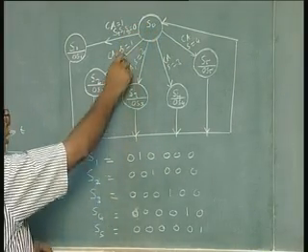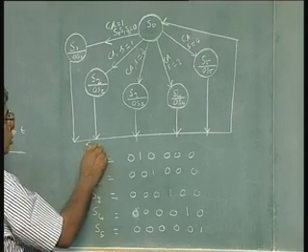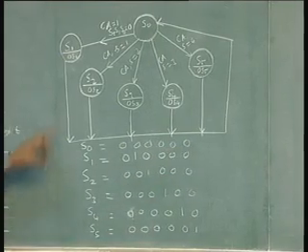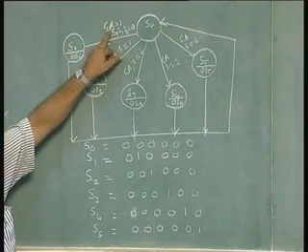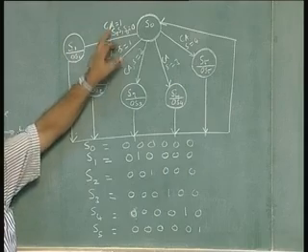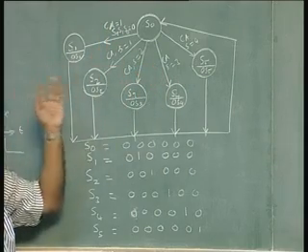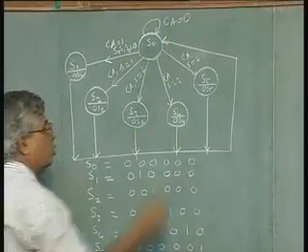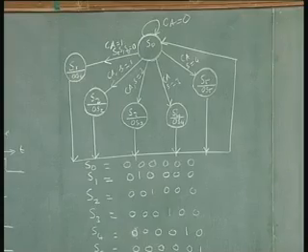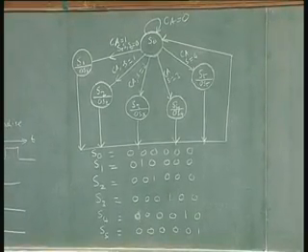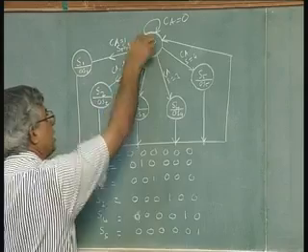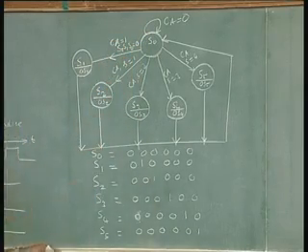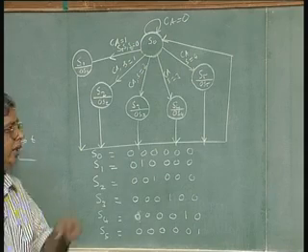and whenever the CI is 1, the coin accept is ready. Only with the coin accept high will any activity happen, because when the coin accept is low, it is going to wait. So if nobody puts a coin, the machine has no work. So, when the coin accept is low, the machine stays in the reset state, and if the coin has been accepted, somebody has put in a coin, the right combination of coins,